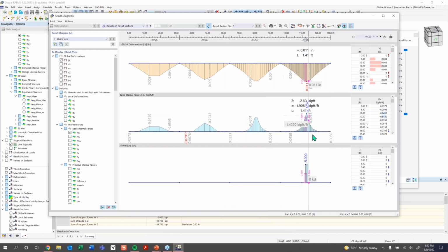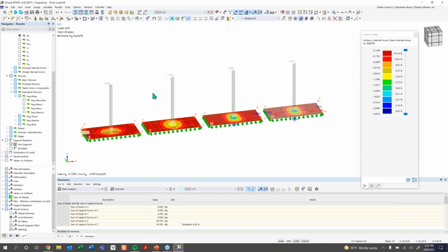Click OK. And now you can see that our smooth range is applied. We can also take this smooth range and we can move it throughout our result diagram here. So we can just keep that right there. This is usually just better for singularities, but as you can see the smoothed out results here, and that gives you a way to distribute the results within the result diagram. So I'm going to exit out of that.